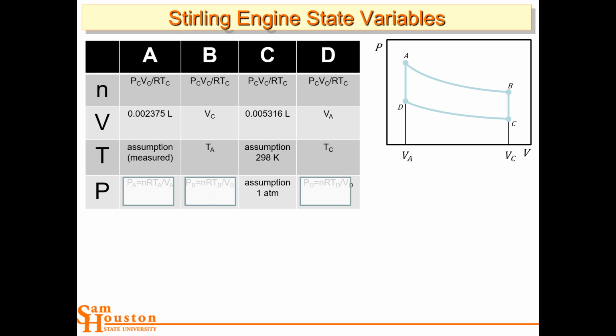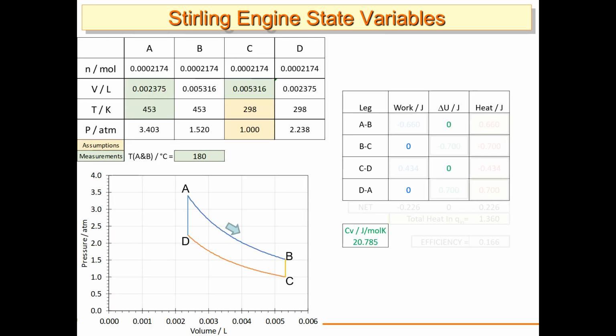And so that's what I wanted to measure between last lecture and now. I ran the Stirling engine for a little while in my office, then blew out the flame and touched the thermocouple to the glass. Like I said, the maximum temperature it got to was jumping around, but the highest one I saw was 180 C. And so then I was able to fill out the whole Stirling engine state variables table. So this is it here. And I've put this spreadsheet up on Blackboard.